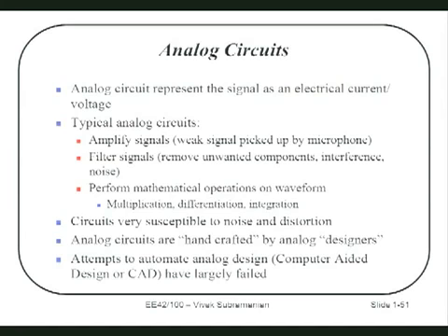For example, all devices have a thermal noise associated with the fluctuation of electrons because of temperature. That is an internal noise source to your systems. EMP is arguably the extreme form of external noise as far as the user is concerned, because he didn't intend for that huge signal to get onto his source. So noise is essentially stuff we don't want on our signals.